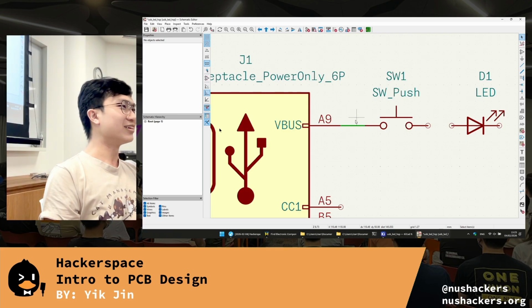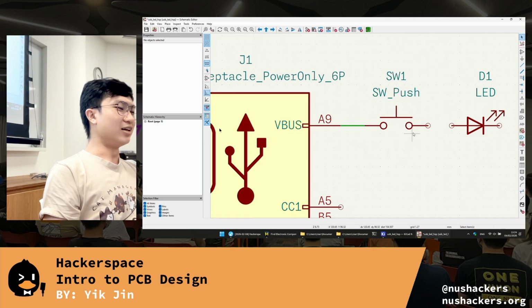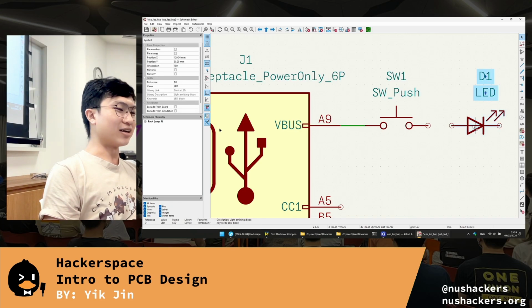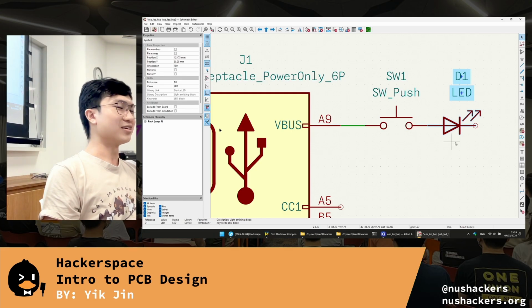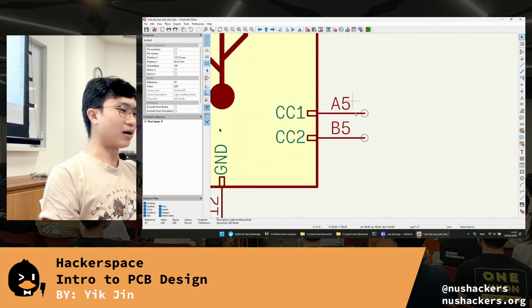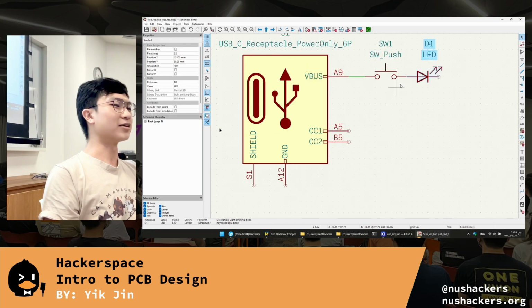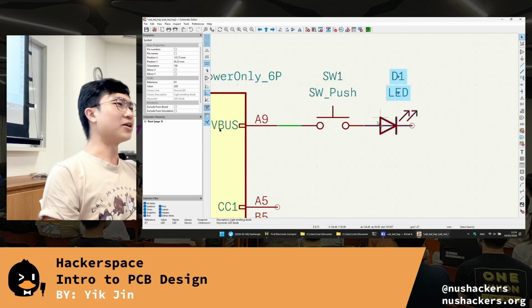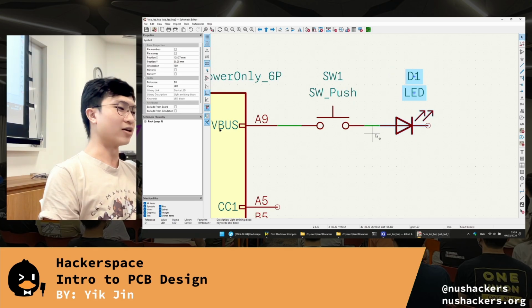If I literally just place it like front and back, off each other, is that actually connected or is it just visual? If you place them on top of each other like this, yes, it's connected. Oh, okay. You know it's connected because this bubble disappears. This bubble is the unconnected bubble. So when you connect it, and then you drag this component out after you connect it, the wire will be there also.